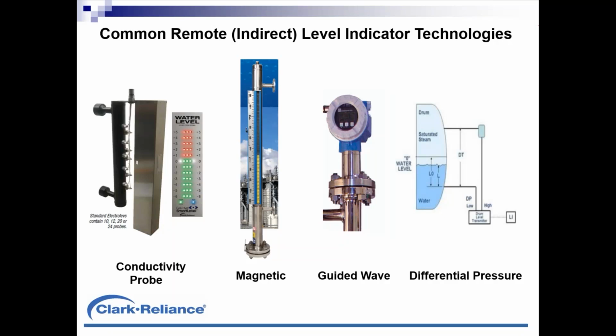Second, we have the magnetic level indicating devices, and that's a stainless steel chamber. And you'll notice the long leg vertically below the lower side connection there. That's very typical among all manufacturers, because the way these units work, they are designed with an elongated float, and in the upper end of the float, there's a magnet that attracts or repels the attached level indicator.